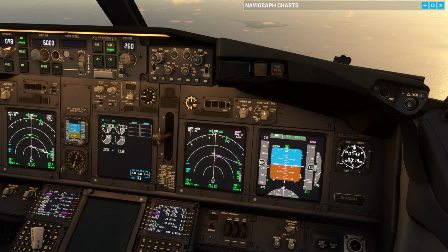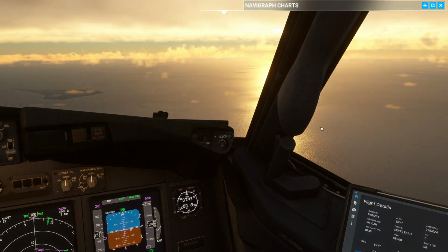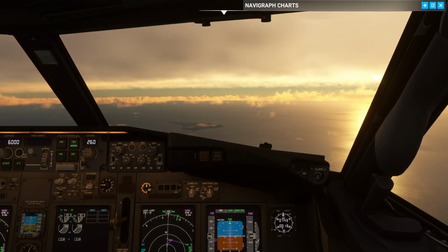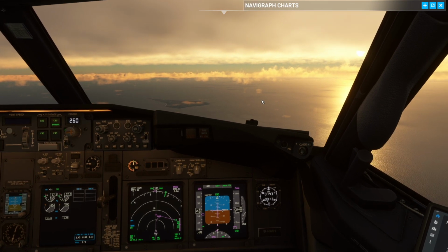What we're going to do is I'm going to show you exactly step by step how to fly it. I'm not going to follow the exact procedures in real life, and what I mean by that is the two-pilot cockpit, because doing that would take half an hour with all the briefings we have to do. So take this video today as the technical steps to get the 737 to fly a non-precision approach, and in our case it's going to be an RNP approach. But the steps we're going to do today are exactly the same for every single non-precision approach you can fly. It doesn't matter if it's a VOR, an NDB, or what it is. You can fly it in the exact same way.